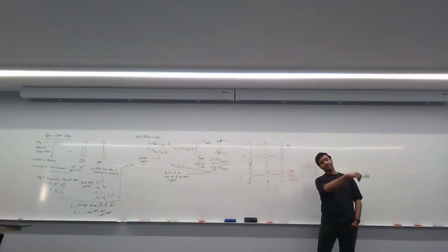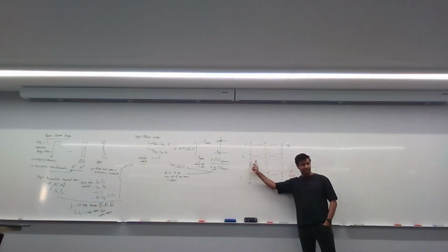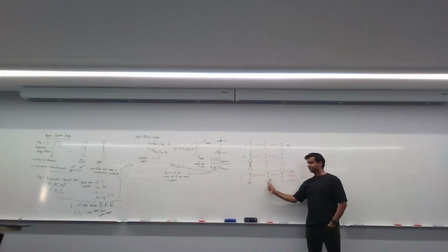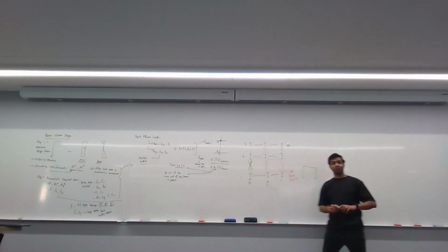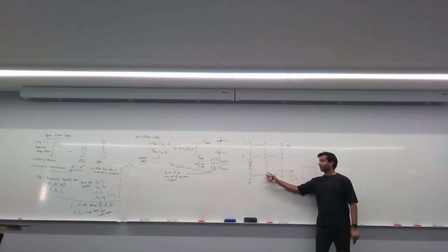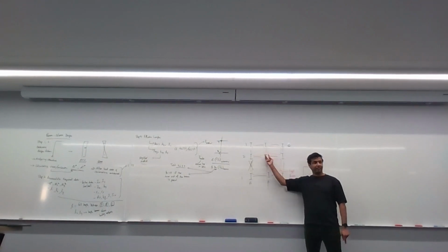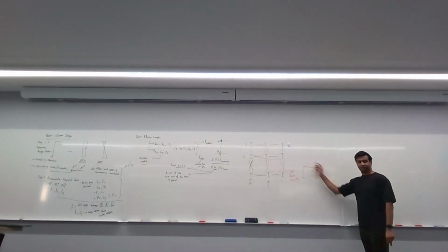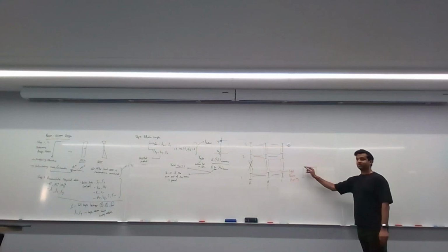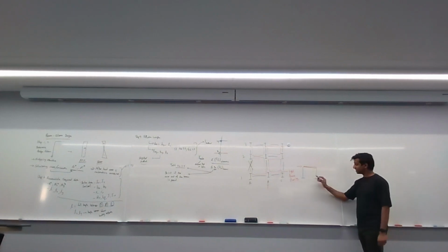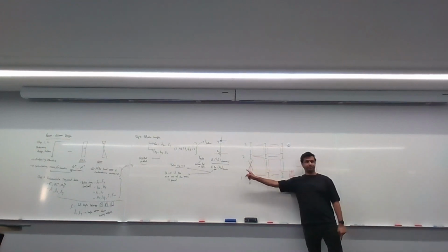Let me flip the question and ask you again. If there is no bracing here, is this a braced frame or a sway frame? That's where the problem is, because if there's no brace here, you just have flooring here. That's like saying this is your frame. You have flooring here, but that flooring is not stopping any movement in this direction. The whole thing can still sway. You need something to do that, so you need a brace.